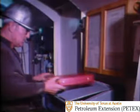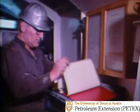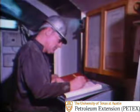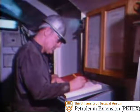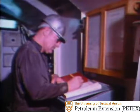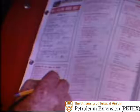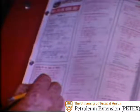A worksheet containing all the necessary steps and instructions is important to the driller's method of kick control, in order to properly execute the operations with confidence, to eliminate wasted effort, and to ensure that successive steps are performed in the correct order. Use of a worksheet to kill a well may seem unnecessary, but the step-by-step procedures can be difficult to remember, especially when there are trying conditions, such as weather, stress, or other difficulties.